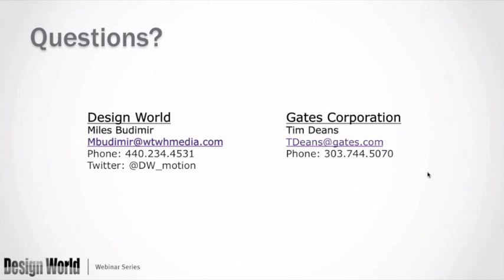I work for Gates, so I know our catalog. Section C of the Gates catalog is going to tell you your chemical compatibility with probably about 90% of the chemicals that are out there, and the particular tube stock of the hose. And remember, the tube stock of the hose, generally say a nitrile or Viton or PTFE, is going to be similar to the flexible material that an O-ring or a seal would be made of also.